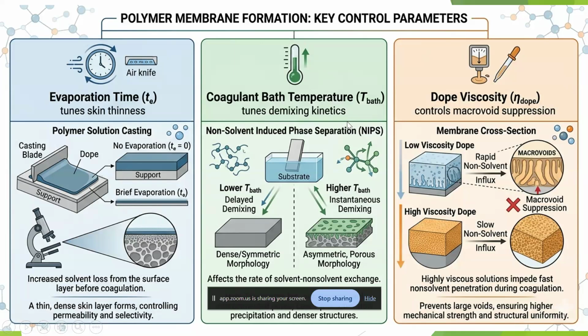If the coagulation bath temperature is high, the skin of the polymer will be extremely porous and weak. If it is very cold, for example 4 or 5 degrees, then it will be extremely denser and can be used for gas separation applications and some other niche applications.